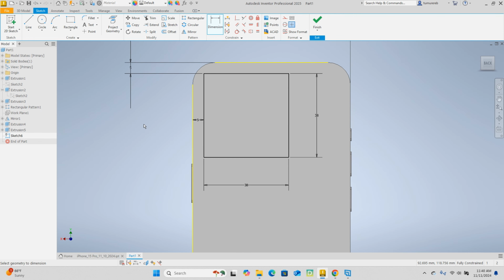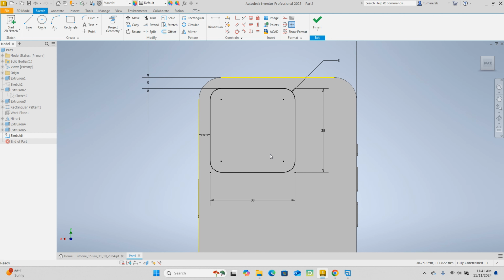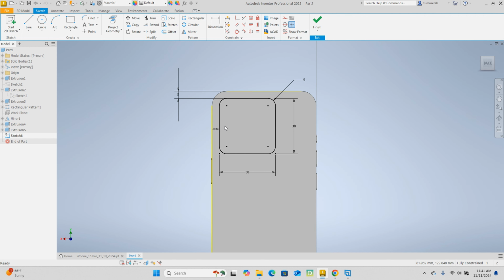Okay. You also round these corners. So go to fillet. What was the radius? 5. Select this guy. Select this guy. Select this guy. All we've done so far is what? Extrude, fillet, and we use the mirror command and rectangular pattern, but you've seen that before. All right.